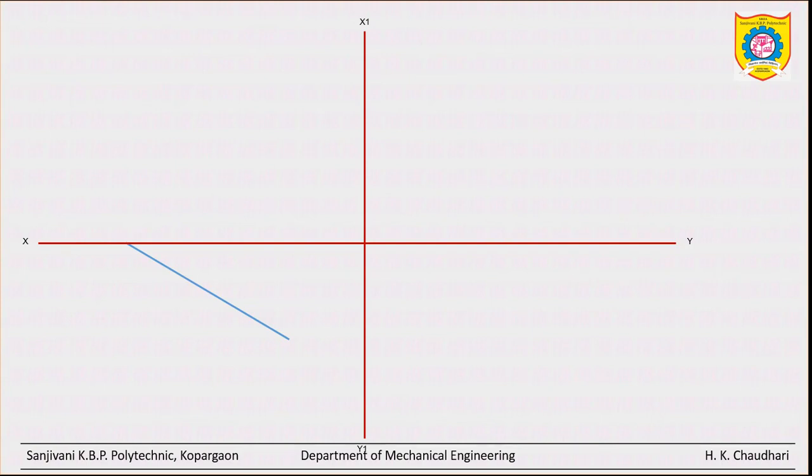So make a line inclined at 30 degrees to xy. It is in the top view. So considering this inclined line as a side, draw the square, correct? As usual, you can draw a square in this way of size 50 mm.